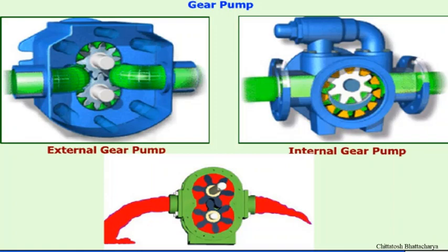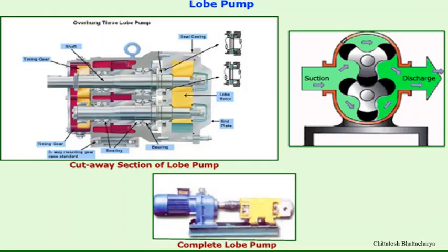Lobe pumps are utilized for supplying acid and alkali. Two lobes are mating with each other and they suck the liquid continuously along the axis and discharge the fluid axially through a sealed chamber. They are placed on 2 shafts. One is the driving shaft, another is the driven shaft. Both are supported with bearings, and there is a compact sealing arrangement. These types of pumps are specifically used for the transfer of acid or alkali, as these pumps are very smooth in operation.